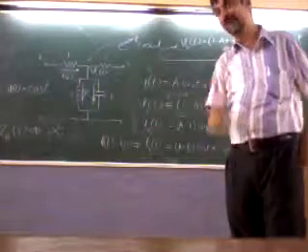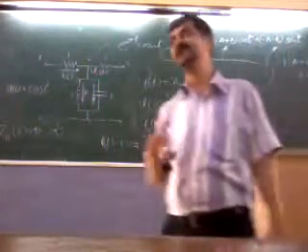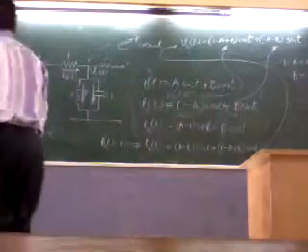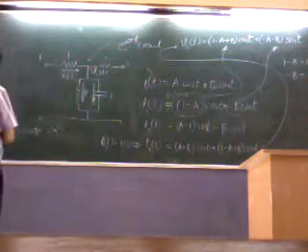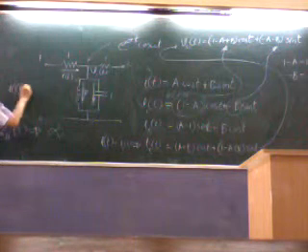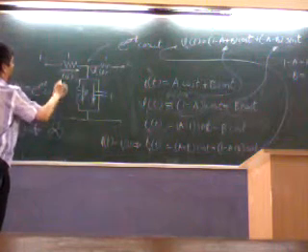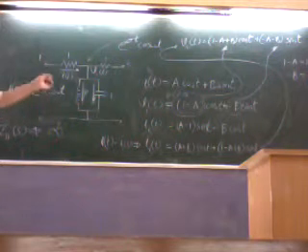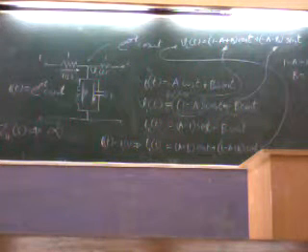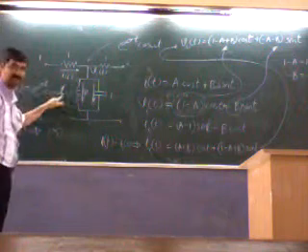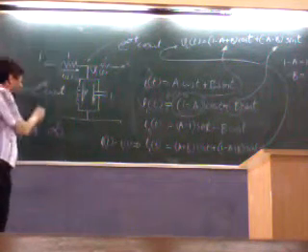In that situation, if I apply a constant current source as input, means instead of applying a voltage source, if I apply a current source here, IT equal to e raised to sigma t cos omega t, then we will be getting one particular value of sigma and omega for which this voltage would be 0.